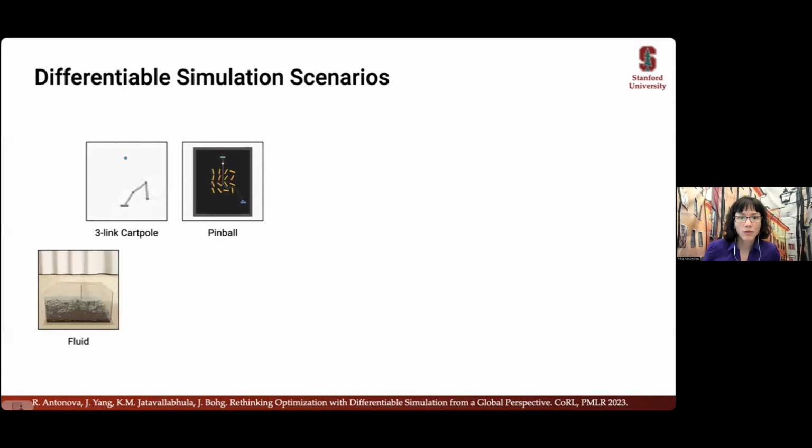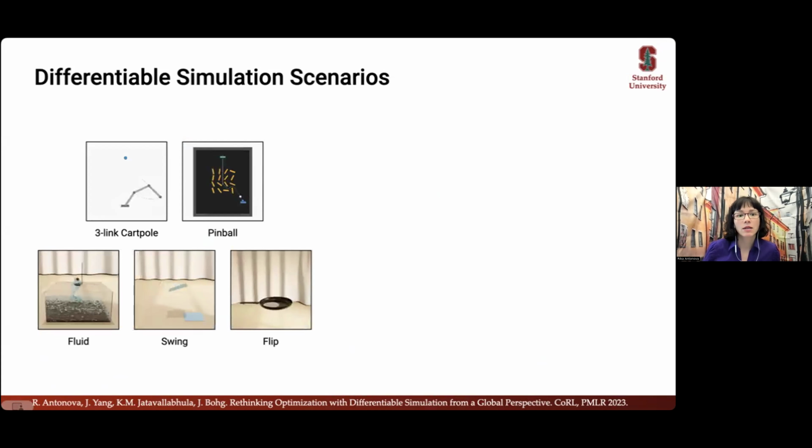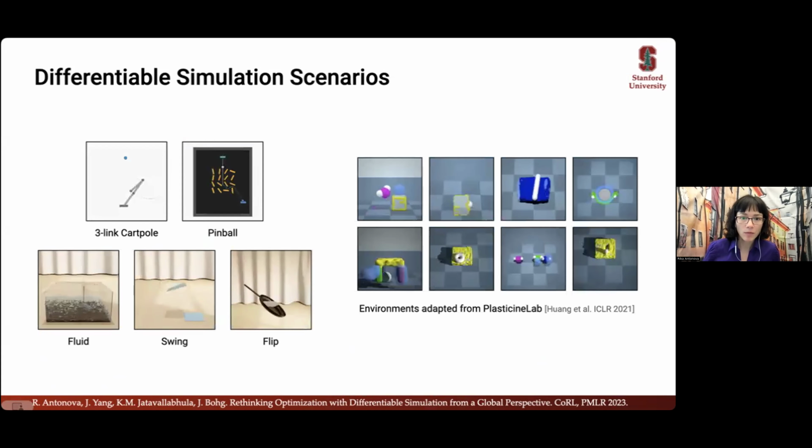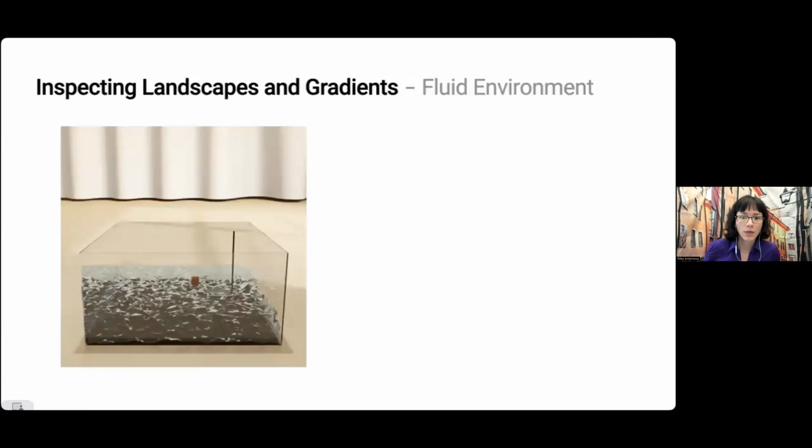So first of all, we constructed scenarios with rigid objects, some benchmark scenarios, some challenging scenarios, to specifically identify what the issues are with gradients for rigid objects. We've also looked at particle-based simulation with fluids and mesh-based simulations with highly deformable objects. And we also incorporated a number of particle-based environments from PlasticineLab that simulated plastic deformation.